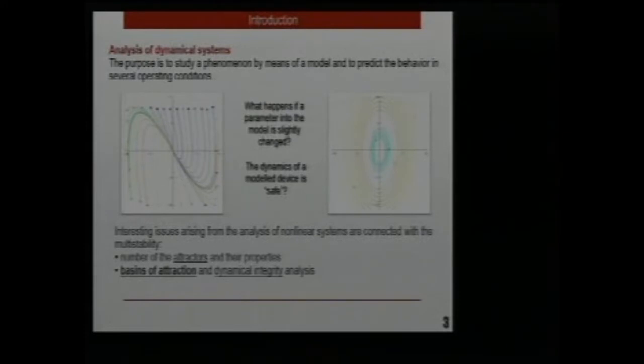Well, nowadays it is well known and realized that stability analysis is no longer sufficient for understanding some real behavior of systems, especially when you get close to bifurcation points. You have to be aware that even if the solution is Lyapunov stable, the basin of attraction could be so small that in the real world you can have imperfection, small but not infinitesimal, in such a way that you can get out from this small basin of attraction, and practically your solution is unstable, even if you believe that it is stable, and theoretically it is Lyapunov stable.